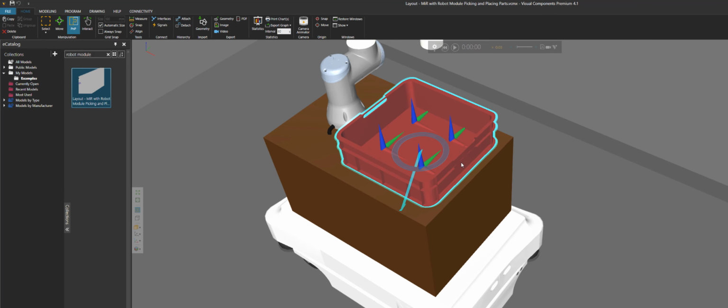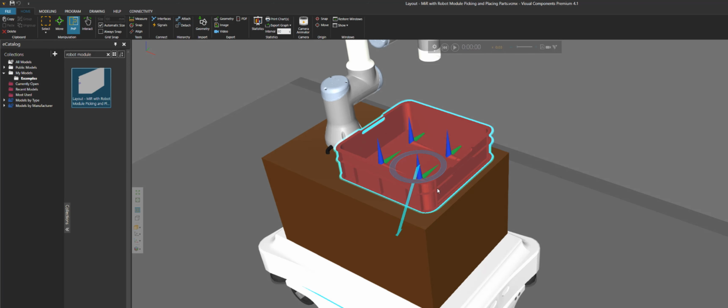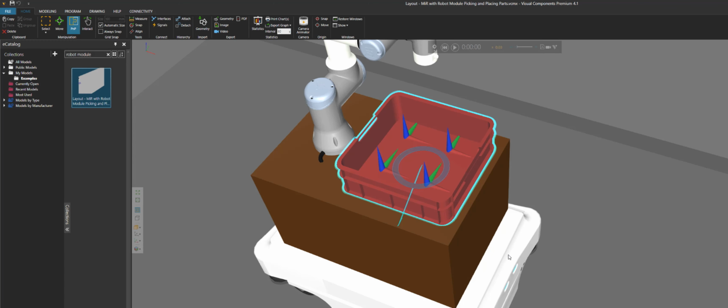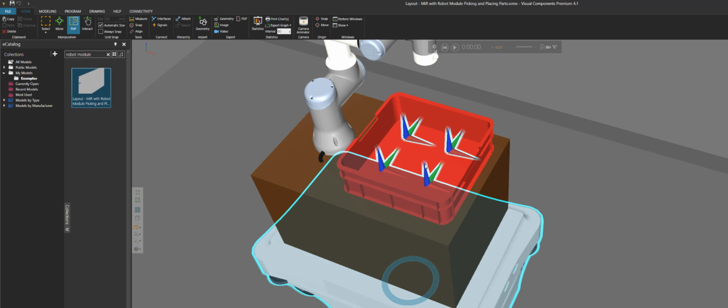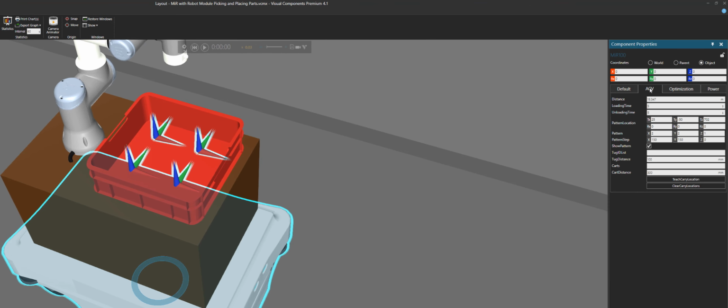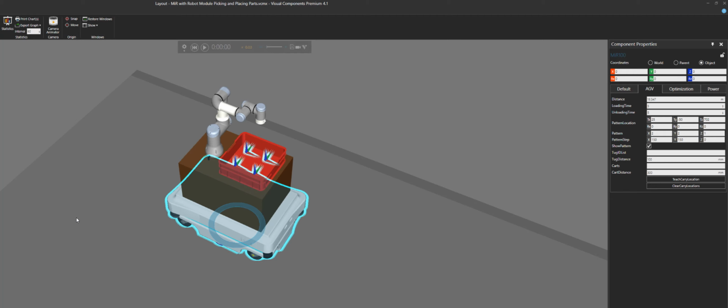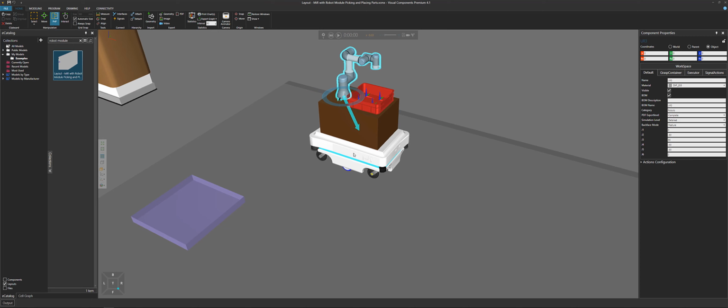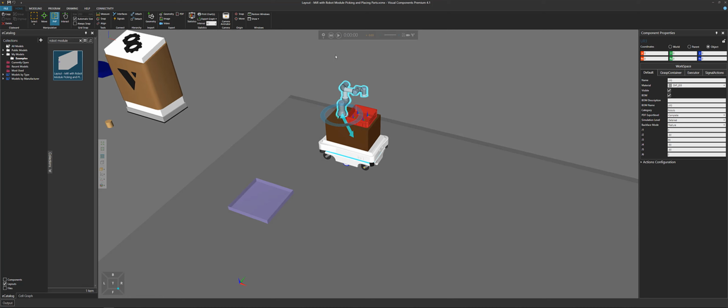We also positioned a bin here, or a tote, or crate. You can call it a tray too. And we position this and attach it to our module too. And for our vehicle, we edited its pattern to be inside that container, which you can see here in the AGV tab in the component properties. So we got the amount we wanted first, so 4 parts, and then changed their location and also changed their step size. So remember, as long as the robot is attached to the vehicle in its hierarchy, it doesn't have to be directly or an immediate child component, it can be used.